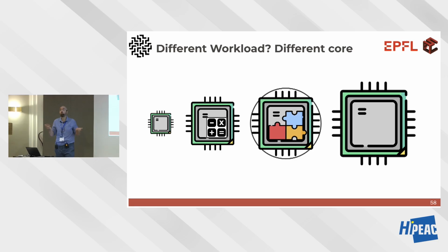So we fetch an instruction, we don't know it, so we want to jump to an illegal routine, but we don't do it because we know there is an external bus. So we give the instruction to the external bus, there's a handshake, and I ask the coprocessor, is it your instruction or not? If not, then it's an illegal one and I trap. If yes, deal with that.